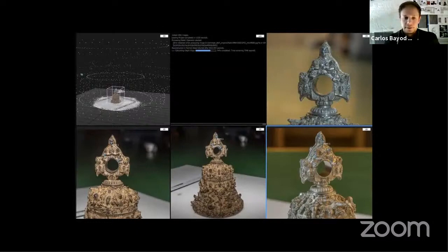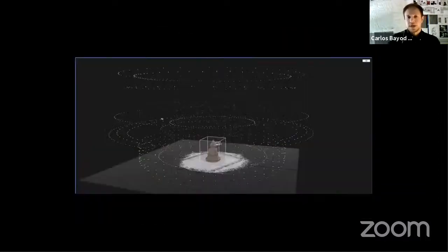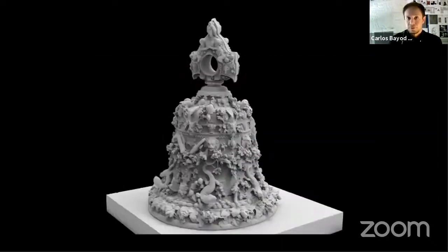But basically, the recording of an object like this with photogrammetry required a very complex approach in which it was necessary to capture the object in two steps, one of them using cross-polarizing filters as a way to filter the excessive glare or reflections from the material, and then merge together as part of the processing these two sets of data, so you could be using the best quality photographic information for generating your 3D model.